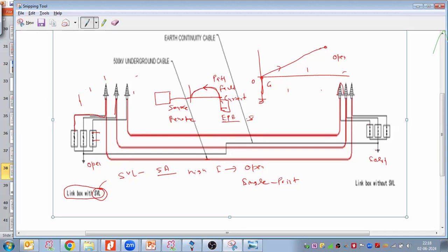Keep this point in mind when we come to earthing. We will calculate the ground current. For the ground current, we take the full fault current IF, then the split factor SF, and then the derating factors. By multiplying these factors we calculate the ground current. The split factor SF is how much current splits between the local and remote earth. So solid bonding provides the current splitting.